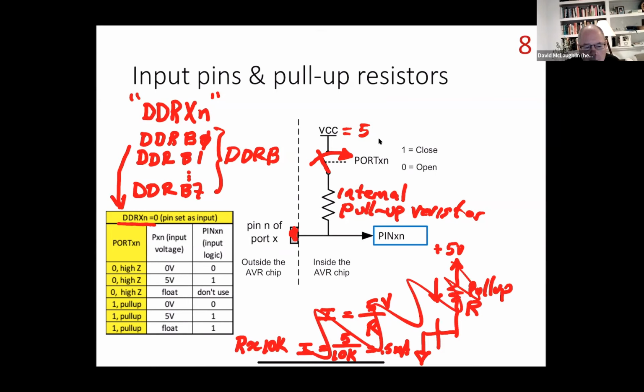Okay, so in order to read a value of a pin, we're going to be looking at the pin register. In our example, we were interested in pin D6 and pin D7, right? Because we're using, no, that's not right. It's 3 and 4, because our inputs are going to D3 and D4. So we're going to be reading the logic values associated with that by reading pin D3 and pin D4.